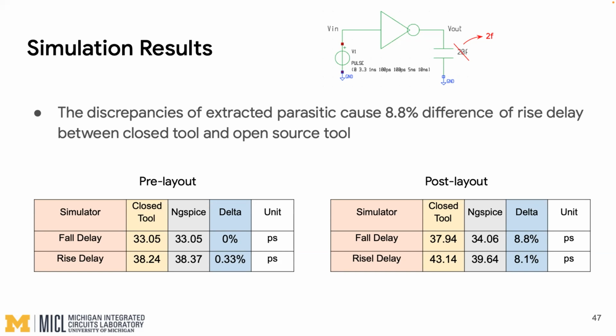The one issue I've seen in the resistance extraction is that sometimes Magic is ignoring stack contacts. I think there's a problem where it's not properly decomposing the stack contacts into individual contacts, and it's occasionally missing them.